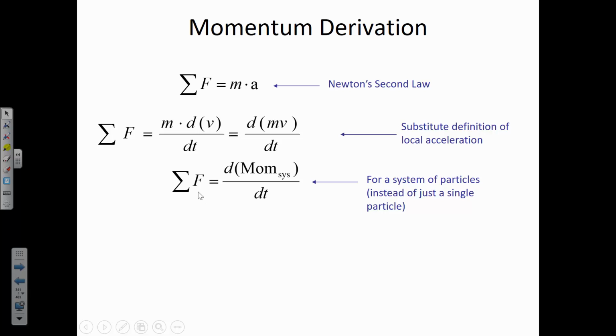In the case of those jet boots, you have combustion inside of the jet chamber, where it's taking in oxygen, burning the kerosene, and the exhaust is going out. As a result of that really high velocity exhaust going out, it's applying a force to the boots. Now, momentum is the product of mass and velocity. So if you want a lot of momentum, because you're trying to maximize the force that those boots can apply, you either have to have really high velocities or a lot of mass.